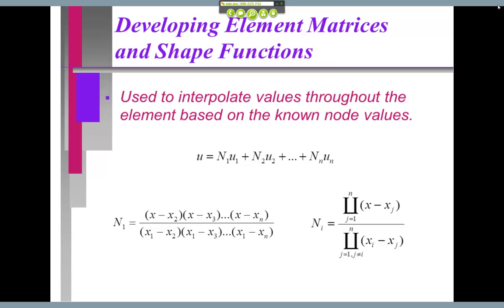All of us have seen some kind of finite element results, and it's usually a very nice gradation across the model, showing different levels of stress. Well, how they do that is basically through interpolation. It's using the corner points where all of the action, the loads, the deflection, everything is being calculated, and basically using that to interpolate any point inside of that 2D or 3D element.